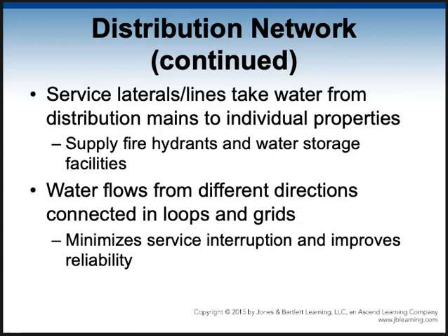We don't want to mix those because the water that gets into the fire protection system sits there for years. And it gets gross, it gets black, it gets stinky, it's horrible. So you don't want that back into our water system. We're going to make it flow freely into anything that is being used for human use, but the fire protection systems, we're going to keep them separate.